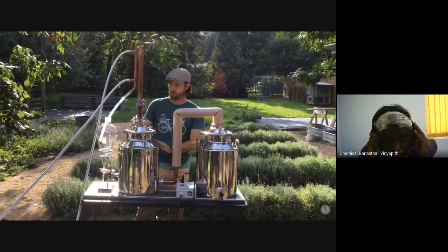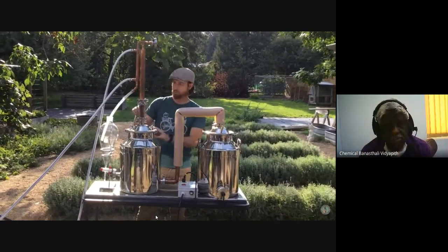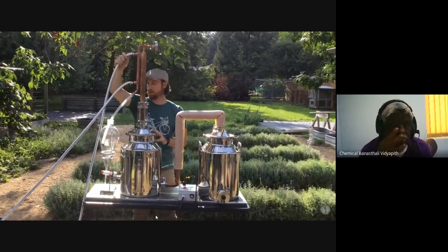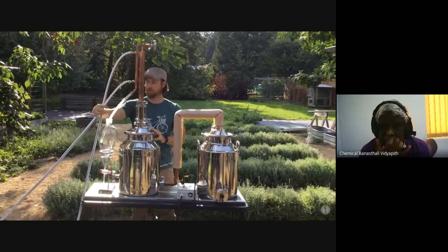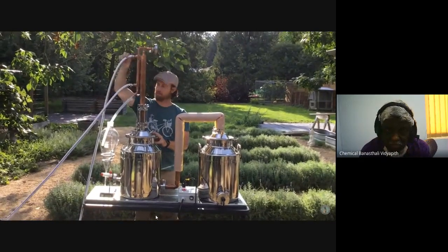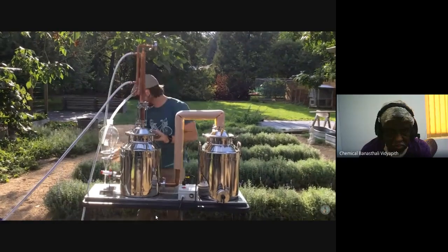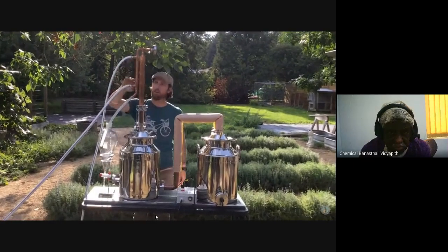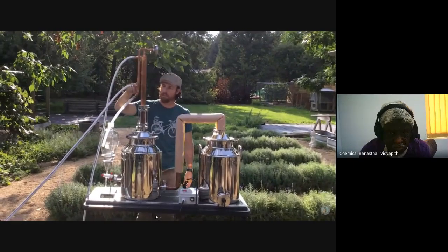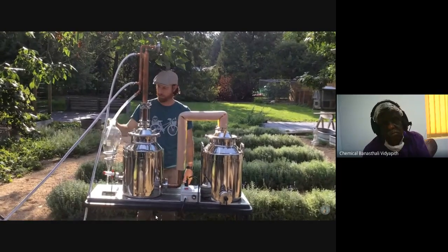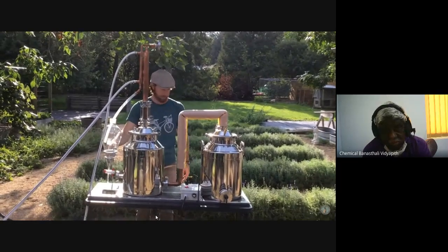So as our steam passes through this column up and out, comes this way, now we have cold water coming from the tap in this pipe, and it's circulating up and through this little jacket, and then back out this way, and that's coming back around and watering our lavender plants. So we run cold water through there, that's our condensing column, and then our condensate, which should be lavender oil and hydrosol, will drip out here into our separatory funnel.